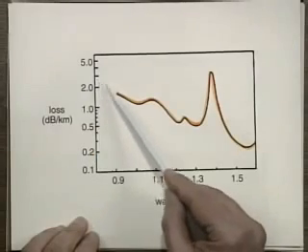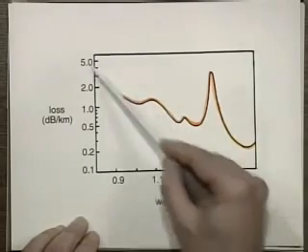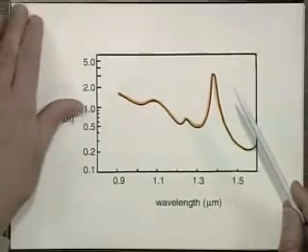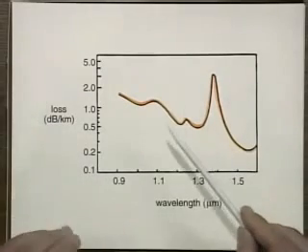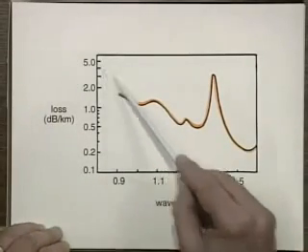And the reason it's small is, first of all, that the total internal reflection is really 100%. There is no loss because of that. And the reason there's any loss at all is because you're squeezed in from one side. On this side, you have what we call Rayleigh scattering. I don't want to get into it right now, but you get scattering essentially from density fluctuations within the glass.